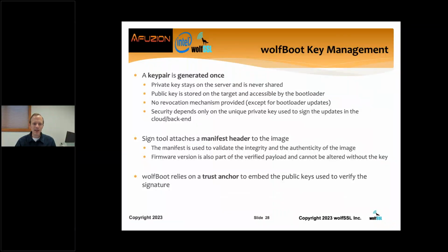We don't have a revocation mechanism provided. So if your private key gets compromised, you'll need to rotate or update the public key on the device, which will most commonly require an update of the bootloader itself. And the security really of this system is going to depend on the security of your private key on the server side. So that's very important to keep private and secure.